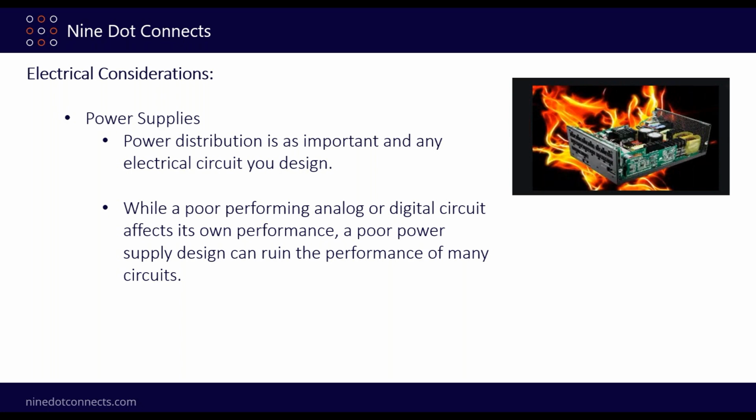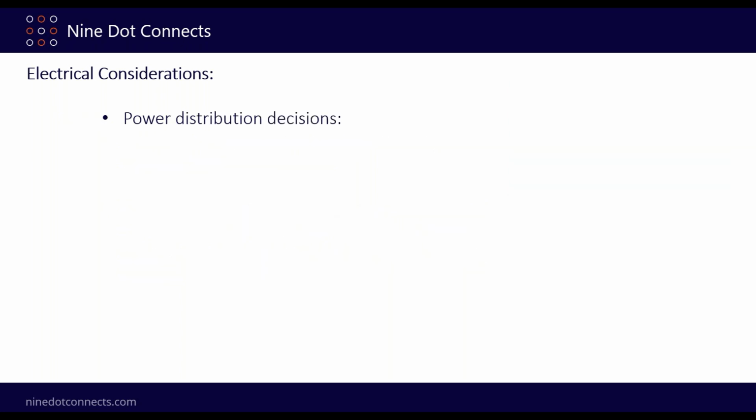So once you fix that power supply and it's working fine, now all of a sudden all these other problems start coming up because now you've fixed that. So that's another reason to get that early on, to make sure you use the right power distribution and make sure that's right, because there's enough problems to deal with without having a poorly performing power supply, because that can just really make your life miserable.